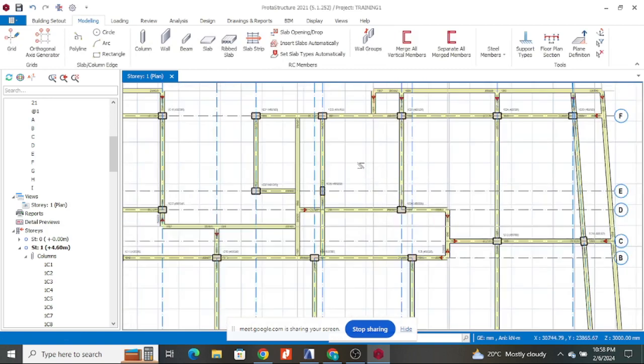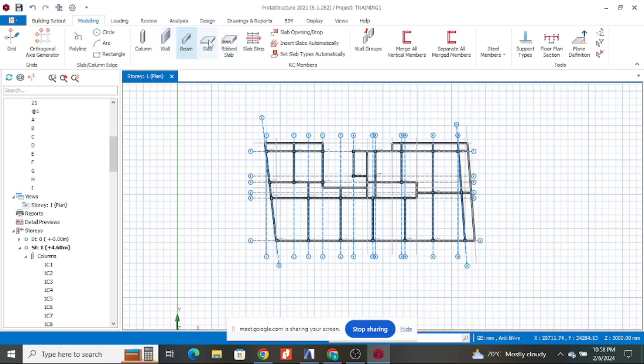Number two, I have a problem with vibrations. Remember these are commercial buildings. And the spans being big, I can design a slab of 150 and it will be sufficient, but it will be vibrating. So the people using it will not be comfortable. Therefore, that calls for me to also remember that these people need to be comfortable while using the structure. Yes, that is why I would prefer 200.